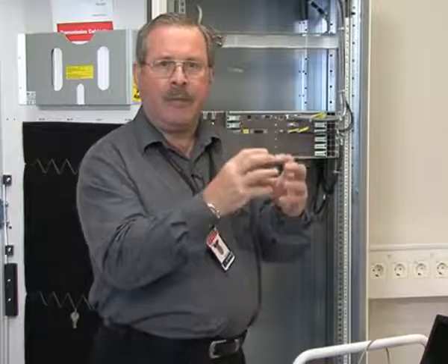The purpose of the radio terminal configuration is to prepare the radio terminals for antenna alignment. Now, this should be done indoors before the radio unit installation. The network element parameter configuration is then done after antenna alignment has been completed. If the link is only a short distance, then you may need to fit or configure in software an attenuator. For more information about this, refer to the Outdoor Installation Manual.